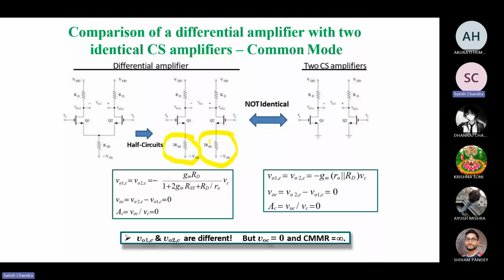Now, configuration of the differential amplifier stage in the op-amp can be based on the configuration. The core configurations are: first, the dual input balanced output differential amplifier; second, the dual input unbalanced output differential amplifier; third, the single input balanced output differential amplifier; and fourth, the single input unbalanced output differential amplifier. The circuit will look like this.